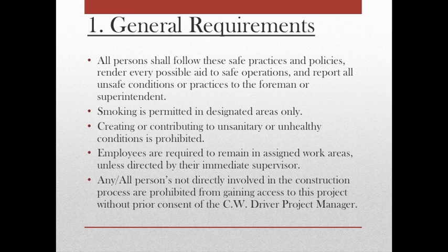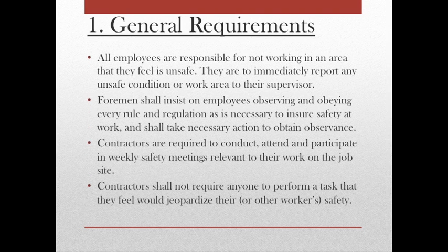Any and all persons not directly involved in a construction process, including children, are prohibited from gaining access to this site without prior consent of the CW Driver project manager. Consent shall be in written form and made available to all CW Driver personnel and or client representatives upon their request. All employees are responsible for not working in an area that they feel unsafe. They are to immediately report any unsafe condition or work area to their supervisor. Foremen shall insist on employees observing and obeying every rule and regulation as is necessary to ensure safety at work, and shall take necessary action to obtain observance.